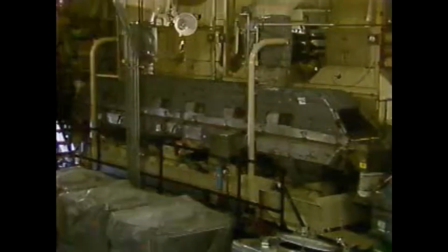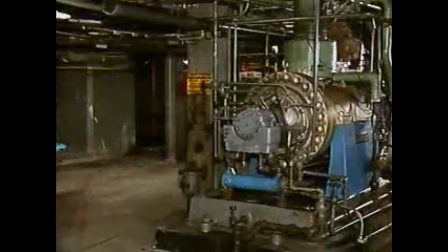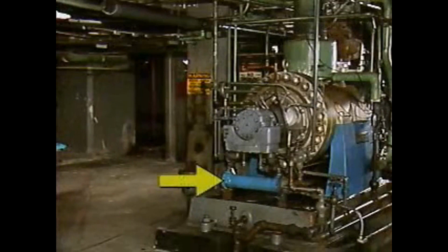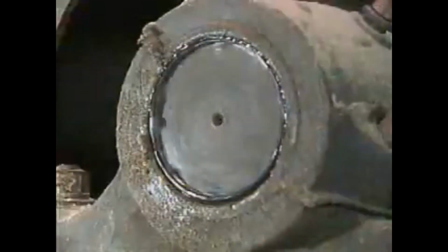Another reason for using grease is that grease may be required to assure that contaminants are prevented from getting between lubricating surfaces. In some high-temperature applications, such as this conveying dryer, grease with a high-temperature thickener is used to keep the lubricant in place. It's possible to use oil in high-temperature situations, but additional equipment such as this cooler must usually be provided to cool the oil.